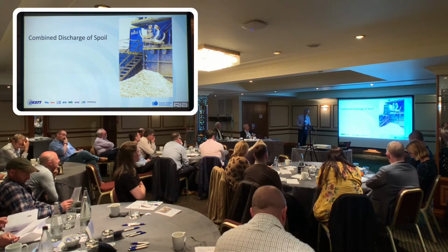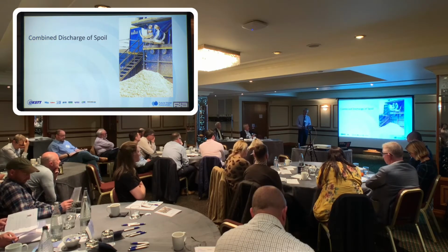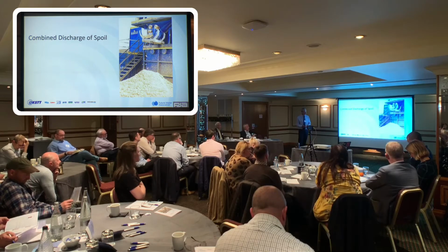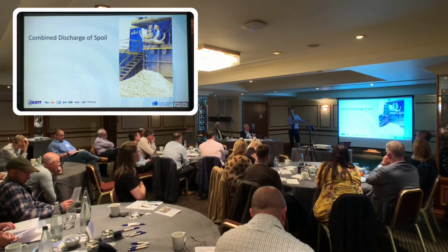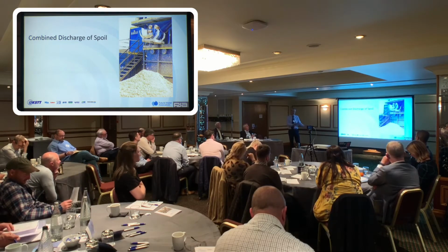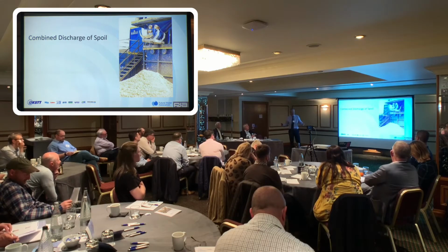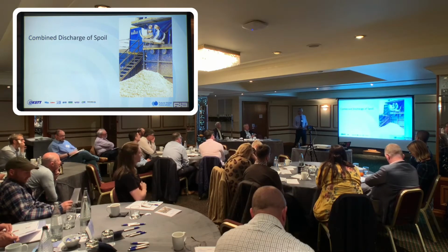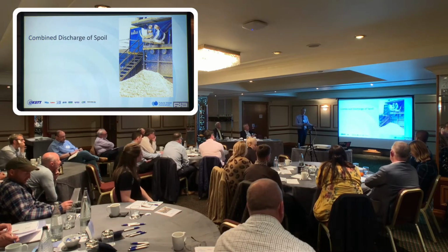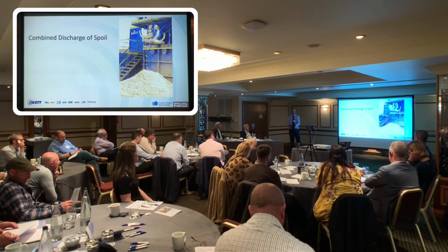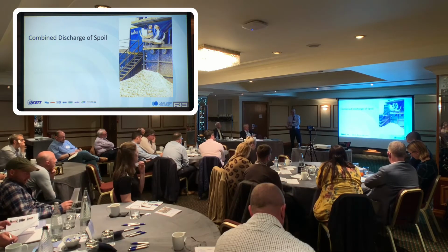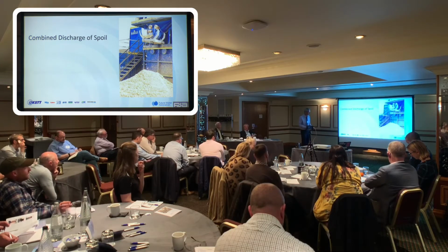There are additives and things that you might put in, but you wouldn't necessarily want to have a high solids mud like you would in a directional drill, because this slurry is not performing the same function. It's purely transportation rather than supporting an annulus. And if you consider putting bentonite into slurry and you're using a flocculant and you're in silty ground, you wouldn't want that, because you're just stripping the bentonite. It's great for the people who are selling you bentonite, but it's not that good for you as a contractor.